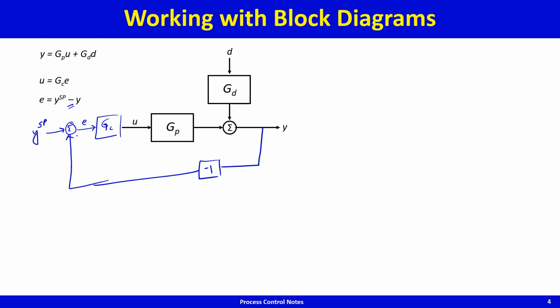That's what the block diagram would be if we want to implement this system of equations, which is actually a feedback control system with a disturbance and a control input to the process manipulated by a controller basing its manipulations on the error, which is the deviation of the process variable from its set point.